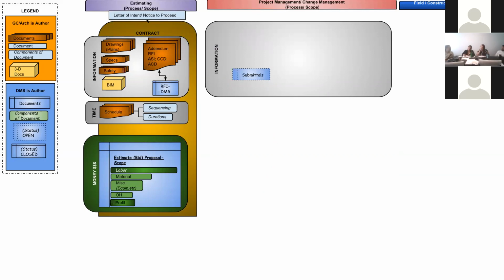I've done submittals where it's taken 1.5 years to get all the submittals completed on a project, because of the way things were phased and because of the requirements. It was multiple rounds of, you submitted this, is that approved? We need samples, things like that. So the submittal process is the process in which we are submitting documents based upon the information that was given to us by the general contractor.